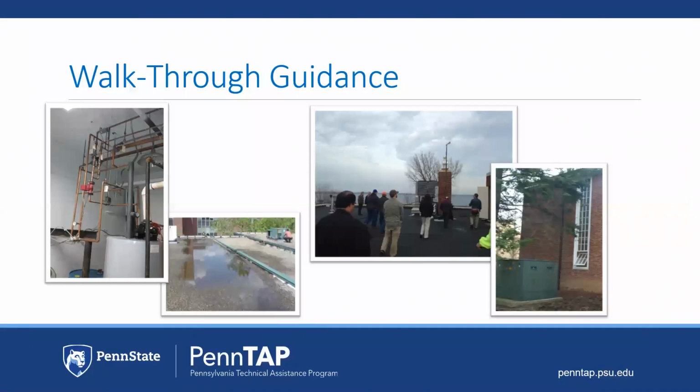Some guidance. You want to look at your building's conditions in both the heating season and the cooling season. You want to look at your operations using your senses. You want to look at your equipment, listen to your equipment, possibly understand the smell of your equipment. Are you burning oil, for example? And also, when safe, touch that equipment. You want to log all of this information and observations during this walkthrough. You will capture these opportunities, and these opportunities will ultimately calculate to potential energy savings. Public service announcement, please consider your safety when doing these walkthroughs.